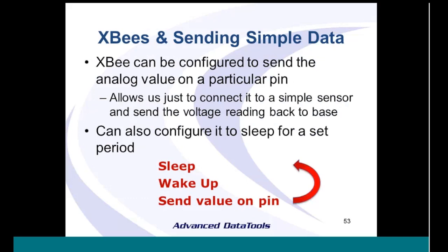Okay, these XBees, because you can configure them through that application, you can set certain values to say, all right, wake up, send a value that's on a pin, and then go to sleep. Okay, by doing this, we don't even need the Arduino anymore. We've got a nice, simple sensor value that we can just transmit.